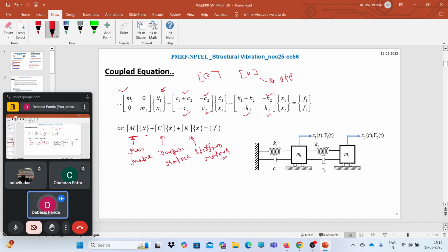We have different kinds of tools, like we can generally do the eigen operation, and precisely we will do that during this course. So now we can see how to develop an equation of motion for a multi-degree of freedom system. Now if we have another degree of freedom over here, say corresponding to m3, and again some force is acting over here, say f3, and the corresponding degree of freedom is x3.